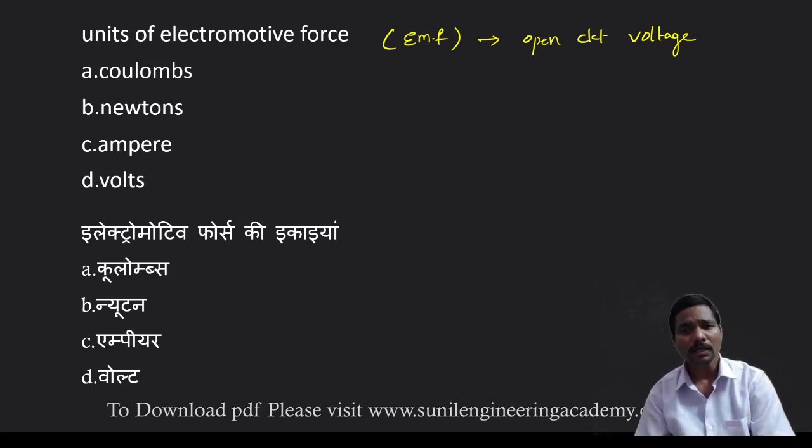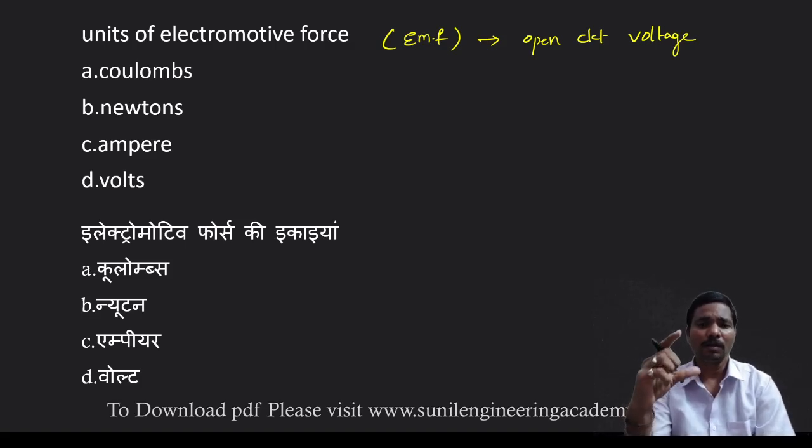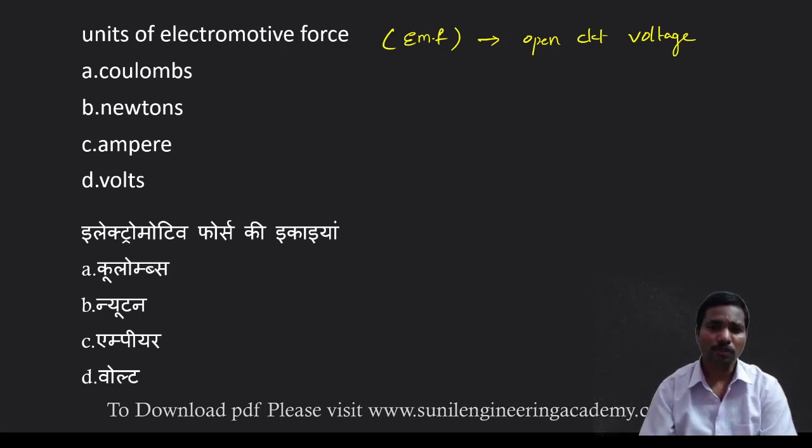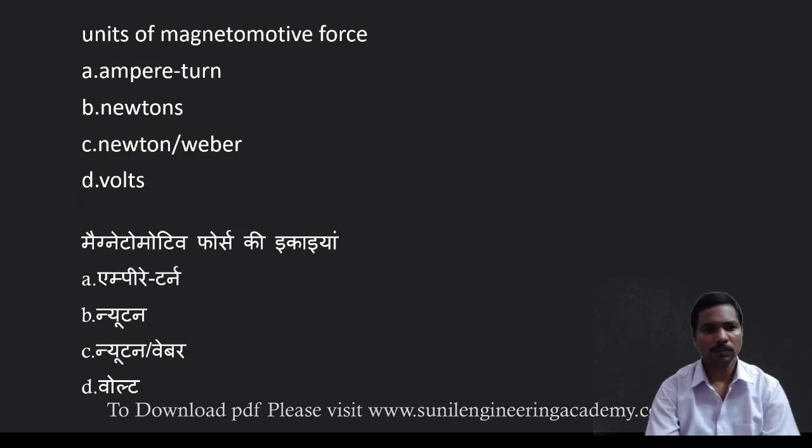If it is connected to the load, then across the load terminals, whatever measurement you get, that is the voltage. So EMF is simply the gross value, and voltage is the net value.